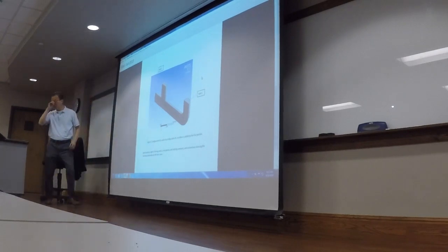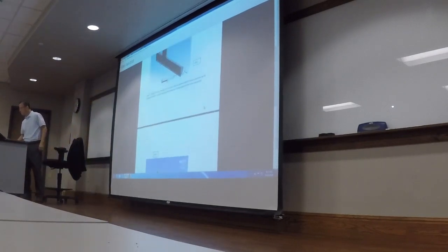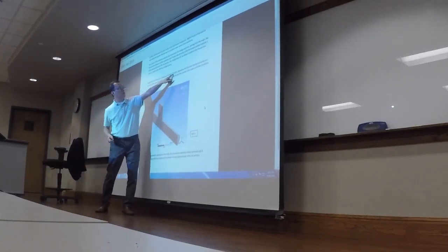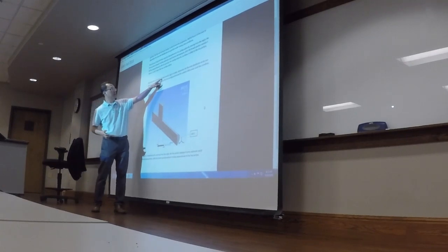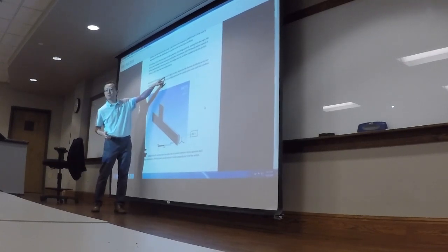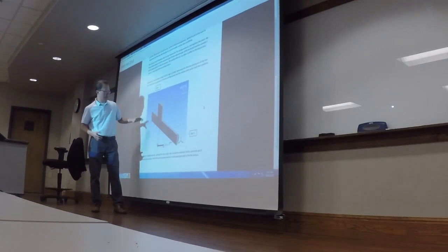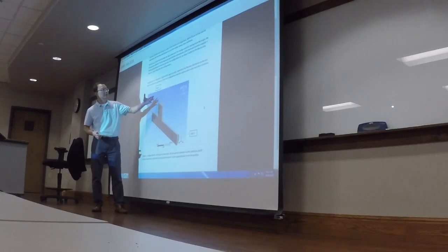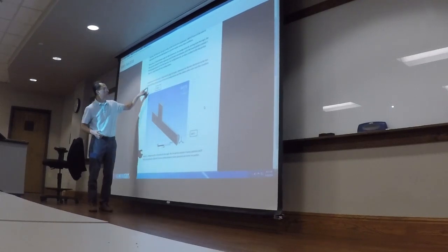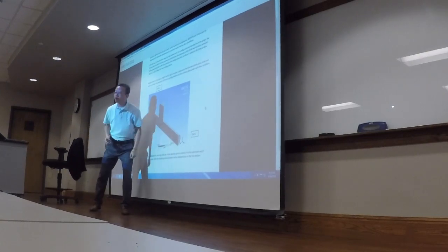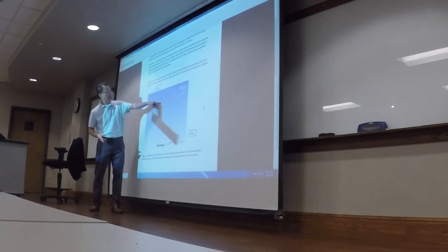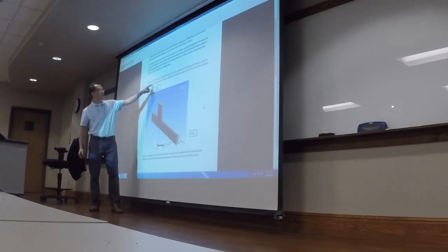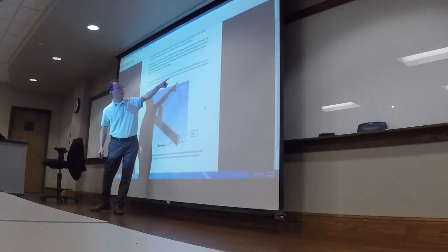Right? And for each of these 2 configurations, let's do 2 flow rates. Assignment for water, let's use water, 1.0 kg per second. That's mass per unit time. That's mass flow rate. 1 kg and 0.1 kg. So there's significant difference. Let's see. Let's determine the flow rate distribution at the 2 axes. We call this axis 1, the line portion, and we call this axis 2, the branch portion. Let's see the distribution, the ratio, and show the geometry of the 2 configurations and the contour plots under each flow condition.